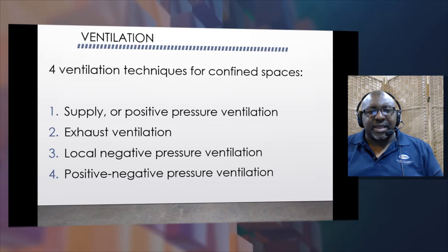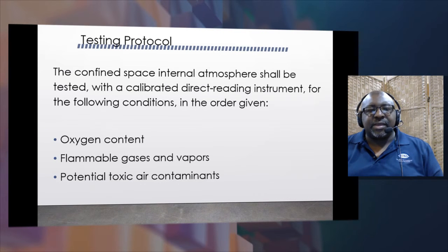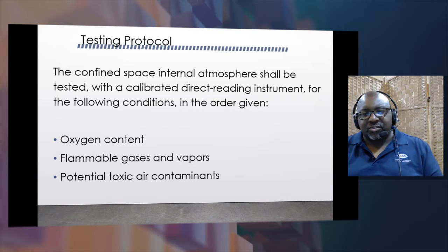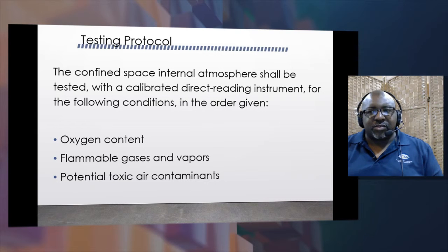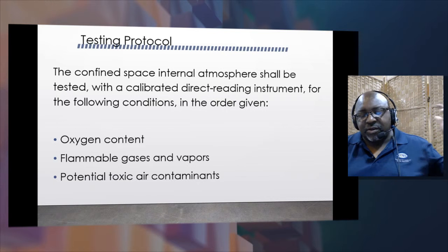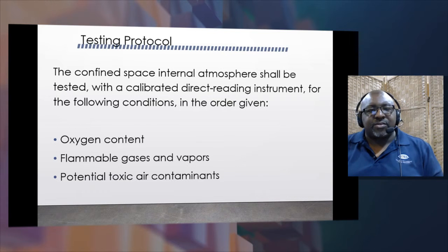That's your 4 different types that you're going to see. And if you are sucking out air from a space and discharging it away from you, you can also be sucking in toxins from any close area, it could be a drainage area, it could be fumes from a nearby car or something. So you really want to blow air into a space more than sucking it out.